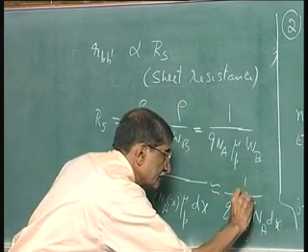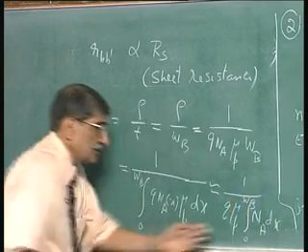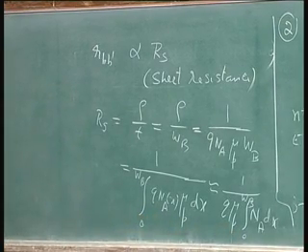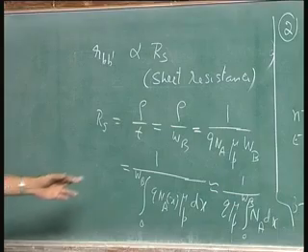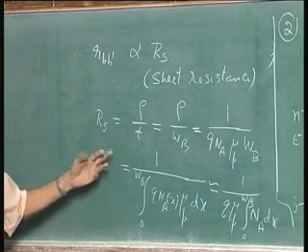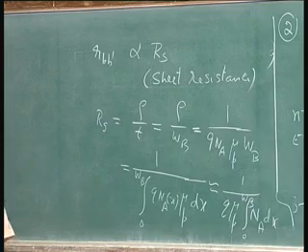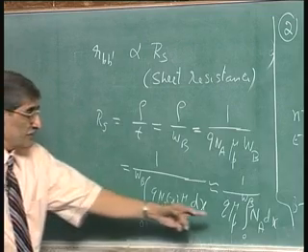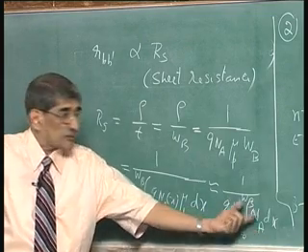0 to WB. This is nothing but total integrated doping. That is what I was telling. Ultimately, what matters is how much is the doping concentration in the base, total number per centimeter square. Either in terms of resistance that you are talking of, sheet resistance, or in terms of punch through voltage also. It is not enough if you just increase the doping, it is as a total doping you must increase.